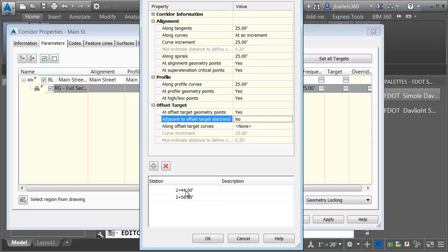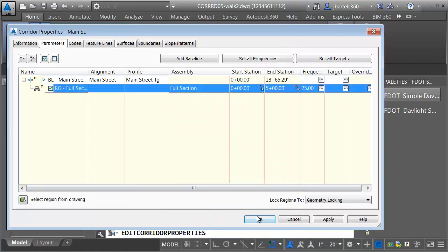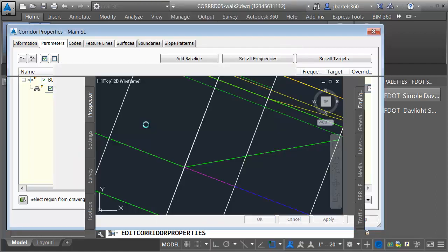Now, I already have insertions at these locations. I'm going to push these out. Let's move this 100th out. Let's make this 243.99, and we'll make the next one 256.01. Perfect. Let me click OK. Let's rebuild the corridor.